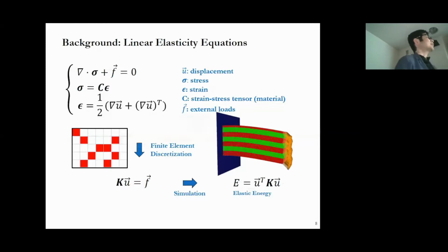The first one is the equilibrium equation, and the second one is the relation between the deformation and the force. It's like Ku equals F in our high school physics. It's called Hooke's law, right? And the third equation relates the deformation, U is deformation, to the strain or stress. It's a tensor. I think you should be very familiar with tensors, and these are tensors to describe the physical motion of these objects. And our goal is to solve this kind of equation, of course.